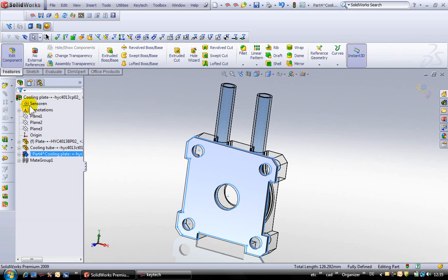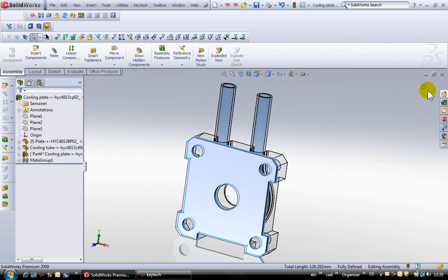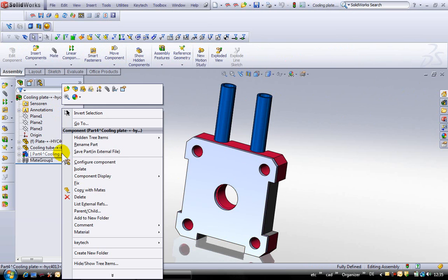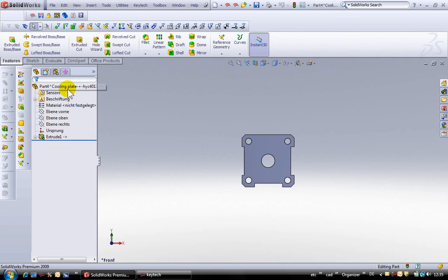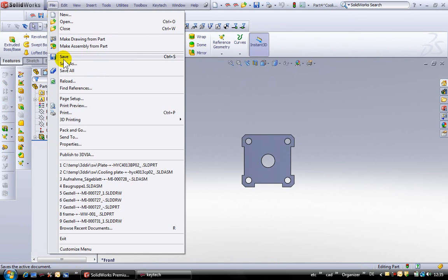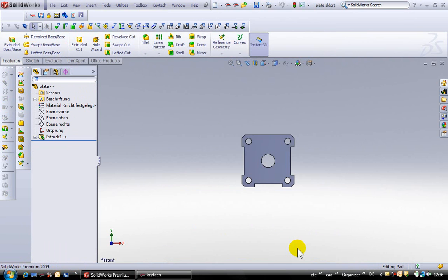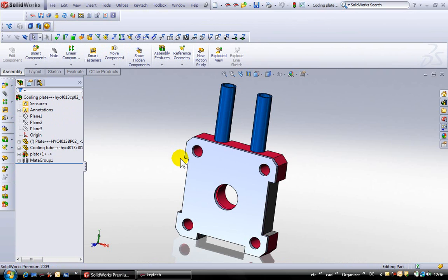I switch back to my assembly and will have completed my changes of this model in 3D. At last, I give a part name for my new part. After performing my changes, I store the edited assembly back into keytech Vault. I use the function keytech store all.